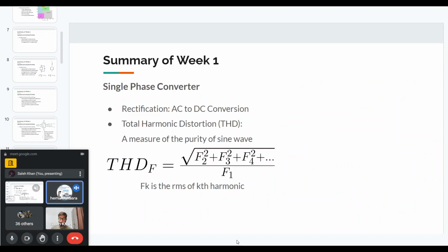Okay, now coming to the single phase rectifier, gate signals applied synchronously to the power supply. I don't understand your question. The gate signals are not applied to the power supply. The gate signals will be applied to the gate driver, and the gate driver will have a constant VCC and a constant VE. So that VCC will be positive constant. Based on the control signal, the gate signals that we want, it will use that positive VCC or negative VE to produce the final output gate voltages.